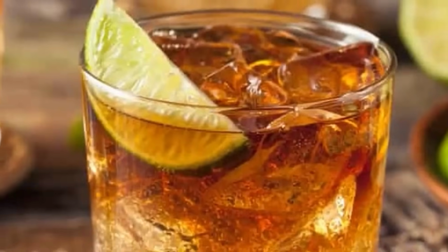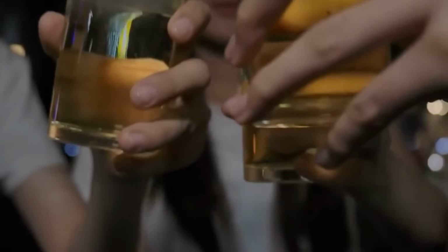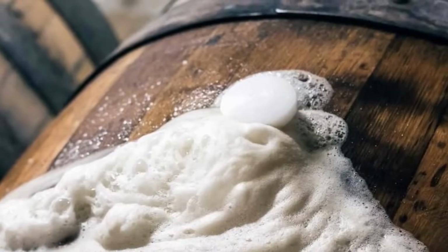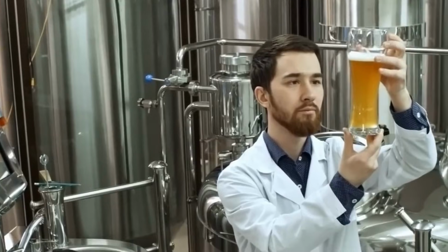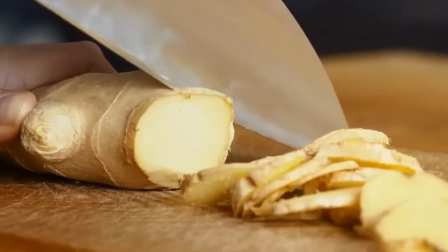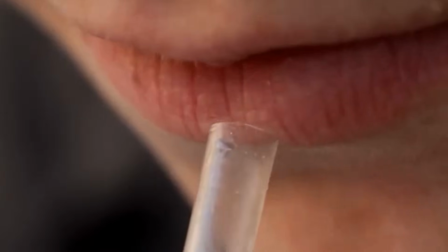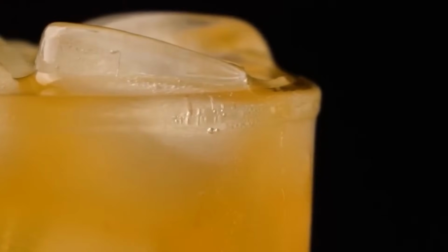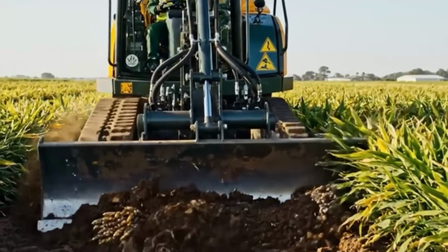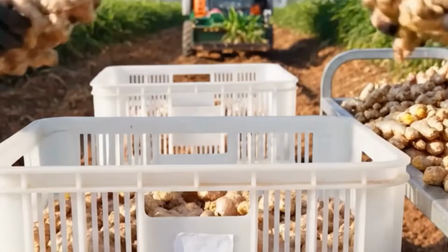The system first applies counterpressure to match internal carbonation levels and prevent foaming. Filling valves open when pressure equalization is achieved. Product flows into the container through gravity or gentle pressurization. During fill, displaced gas vents through a return tube to maintain equilibrium. Fill volume is controlled by valve timing or volumetric flow measurement. Once filled, the valve closes and the container is lowered back to the conveyor.